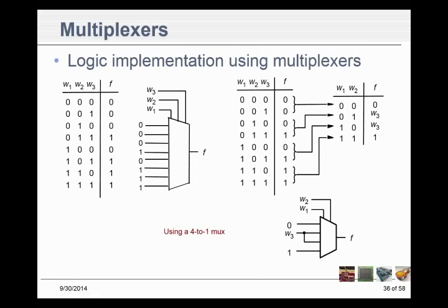Okay, and then we have to have something like this. What if we had a 4-bit multiplexer? We've got an 8-bit here, but we needed a 4-bit. Now look how this is done. We took W1 and W2. Look at these two. They're both zeros. They're all 4 zeros. So that means no matter what, these two are choosing this.